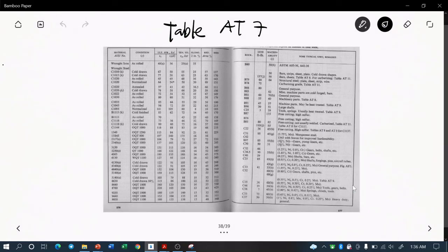So we're going to look up at this table, which is the tensile yield strength. S sub y 55 is the closest, 55 KSI. Okay, 55, 48, 42. So which is closer to 24?